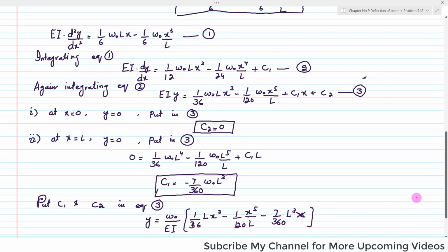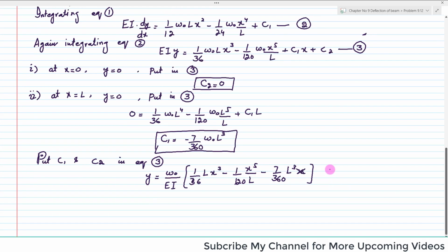Clear? So this is the equation of elastic curve, where y is the deflection and x is the location from end A. Now you can see that in the first part we have been asked to find the location for maximum deflection. At maximum deflection the slope will be equal to 0, so we will take the derivative of this equation.